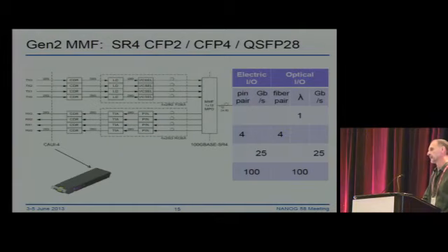Second generation, which is being introduced right now, and the IEEE is actually just completing standardizing second generation 100G. One is called, for multi-mode, the standard is SR4. So it's very similar to the 40G standard in multi-mode that's being deployed, which is 4 parallel fibers carrying 25G wavelength. So if you deploy 40 gig SR4 multi-mode, you could actually reuse that infrastructure for 100 gig SR4. They're both specified for 100 meters. I'm showing a CFP2 form factor, and again, other form factors like CFP4 and QSFP28, which have twice the density, will also become available next year.